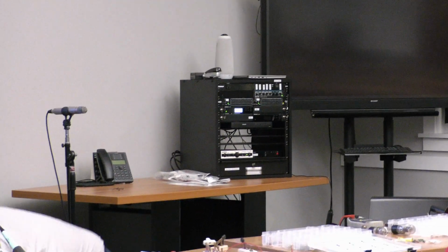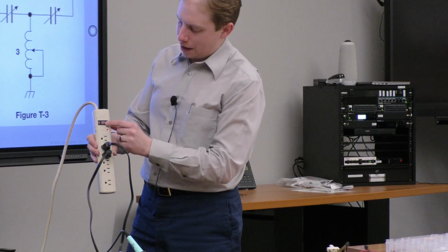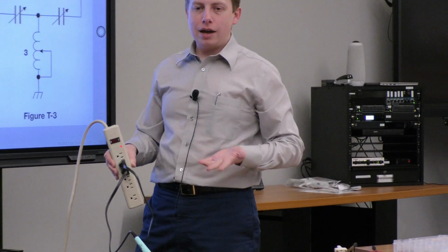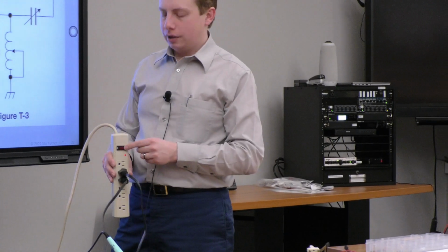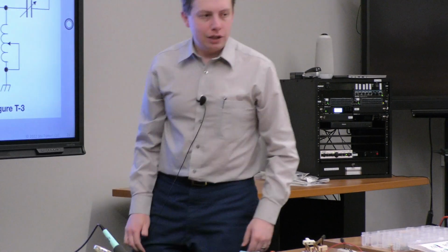Anybody use neon lights anymore? I tell you what, here's another application of a neon bulb. Originally they were used as indicators. They just lived. They didn't burn out. The filament didn't burn out like a traditional bulb. Oh yeah, this one either doesn't have one or it's burned out. LEDs do get exhausted at some point, but they're indicators and they're really cheap. But like an LED, you have to put a series resistor with them because once you exceed the breakdown voltage, they're wide open. They'll blow up in your face if you don't have a limiting resistor. Ask me how I know.